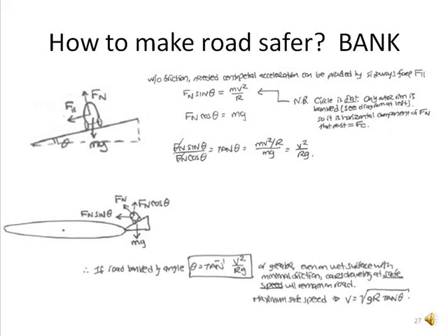Of course, as with most things in engineering, there's a large margin of safety built in, such that in general for a dry surface, this produces a large margin of safety. So you could actually corner it at a much higher speed and still remain on the road surface. However, this is essentially the physics behind road engineering, where we're designing the bank angles of ramps, we're assigning the maximum safe speed on a ramp, and so forth. For cases like the Autobahn in Germany, it would be designed for even handling higher speeds.